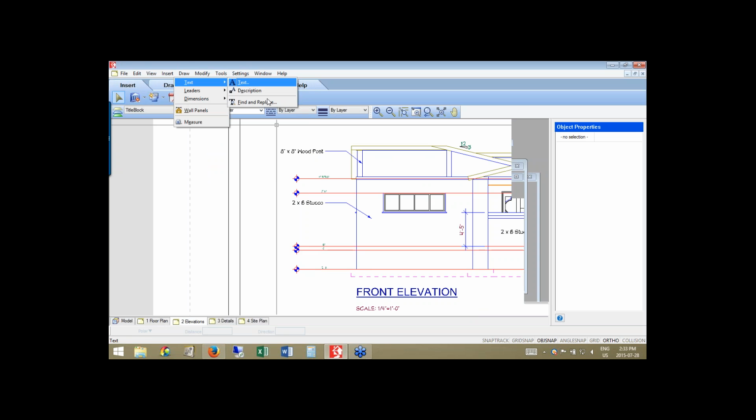Remember also to take advantage of the detail tool called the roof symbol tool, which will put in the triangle and the text for the roof symbol automatically when you define that roof slope. And if you're not sure of a roof slope in a particular area, just like I did today, you can pick those 2 points and it'll automatically define it for you as well.